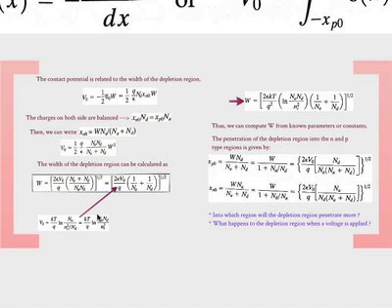Remember, this is the previous example that we solved. We had doping on each side. What is the contact potential? It's given by that equation, kT over q ln of NA ND over ni squared. So you know the contact potential. Once you know it, you can plug it in here with the doping concentration, so you can calculate what xp0 is and xn0 is. Same thing. That's pretty straightforward.